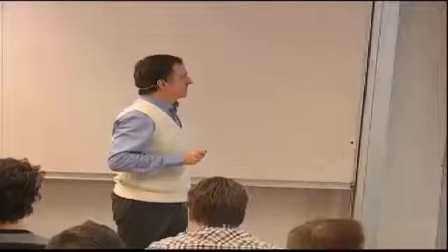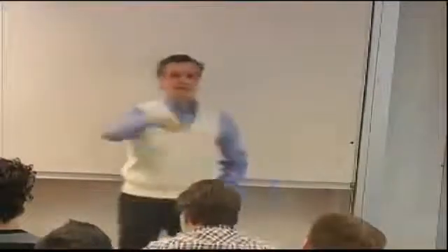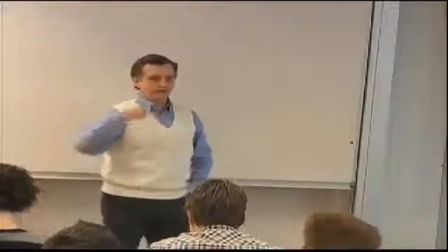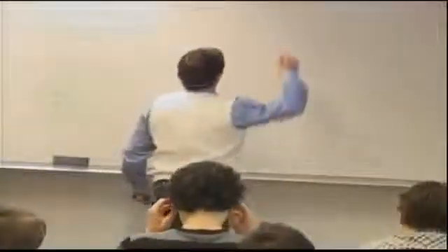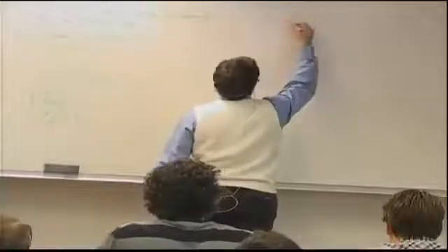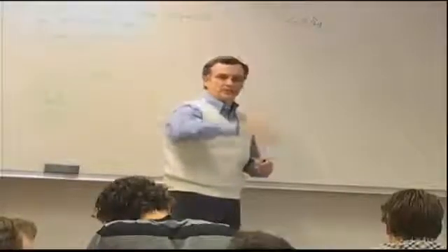we were saying that minimum weight is a big deal, but as far as weight goes, you cannot simply minimize the weight if you pay no attention to the cost. And you've seen all kinds of comparisons between how much money one is willing to pay for every kilogram of weight saved, whether it's a space structure, which is much higher than an automobile, which is much lower. In fact, the numbers, just for now that I'm thinking about it, if you're doing your regular family car, then it's less than 2 euros per kilogram of weight saved that the manufacturer is willing to pay, because that translates to certain fuel savings and so on.